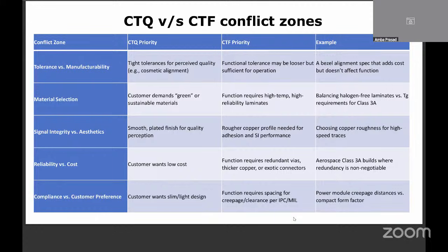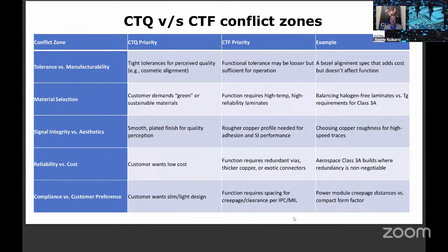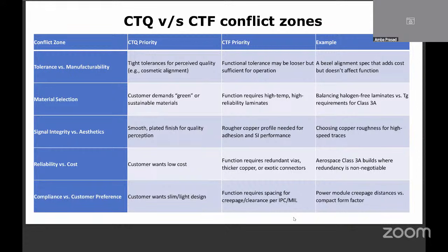And function requires spacing for creepage and clearance as per IPC and military standards. Still, in the power supply region, we want more space. We want more gap. And the power module creepage distance versus compact form factor. These are the issues. So next slide, please.